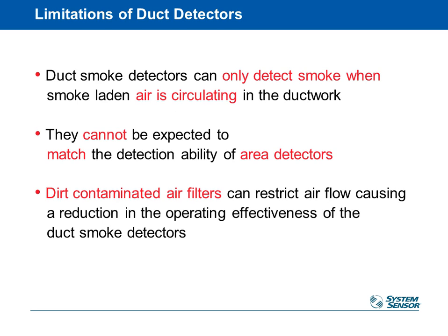So smoke detectors can only do a good job of detecting smoke, obviously, when air is in the ductwork. So if the air handler is off, it's not going to do a very good job of detecting smoke, which is why you don't use this as a substitute for the regular space detectors, and they can't match their ability. And they also don't do a very good job when the filters are all plugged up and dirty. It restricts airflow, which limits the amount of air being brought over to the smoke detector, which makes it take longer to actually detect something.